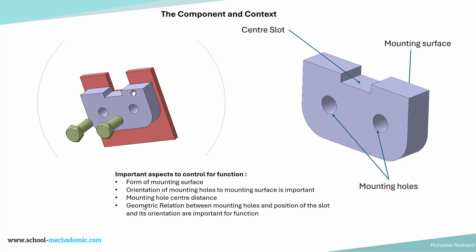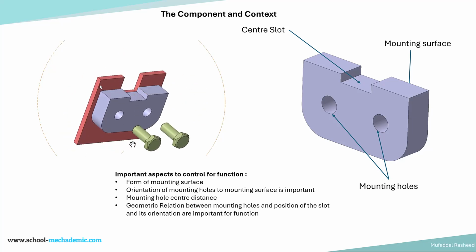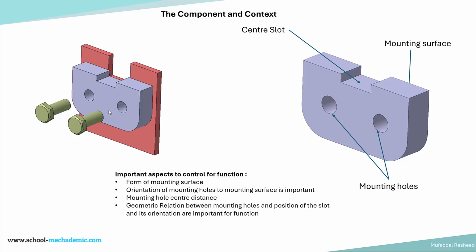Then there is the geometric relation between the mounting holes and the center slot. When we are locating this part based on the mounting holes, then the position of this slot with respect to the mounting holes becomes very important.